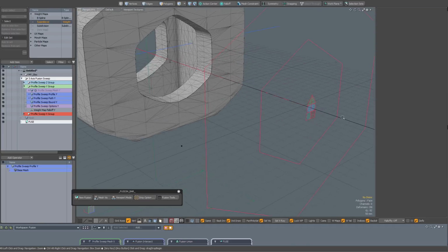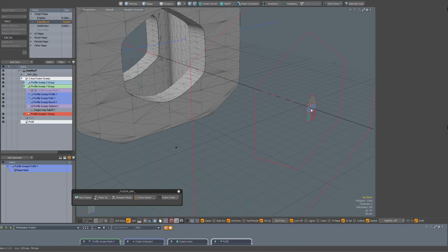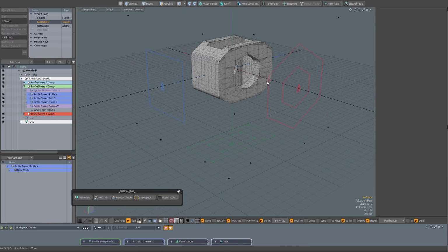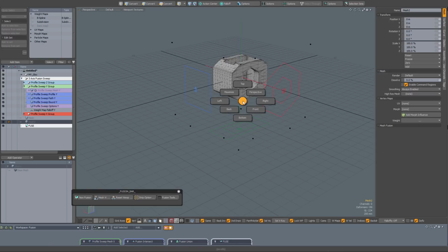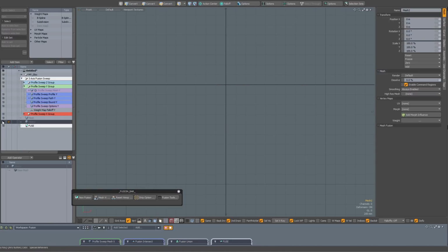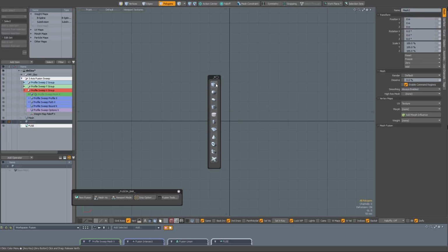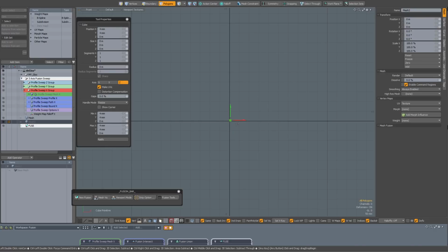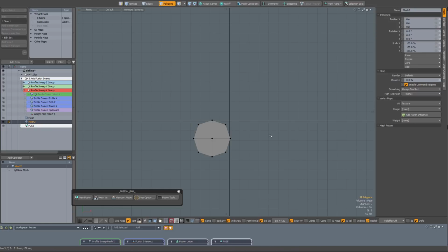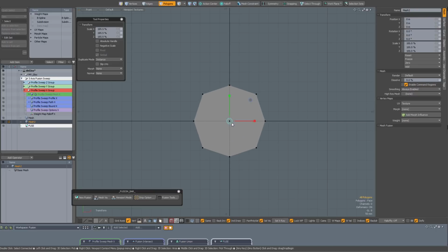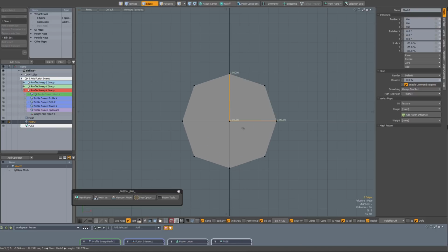As said earlier, you also have these widgets over here, so you can replace the profile with a selection. So if I create another mesh item layer, go for instance to my front view, I'm going to hide everything, create a polygon like that. I'm going to subdivide it, center, select it all, make it a bit bigger. Also make sure that my inner edges are gone, shift backspace, and that remaining vert is gone.